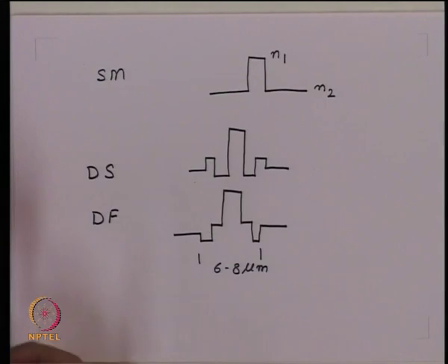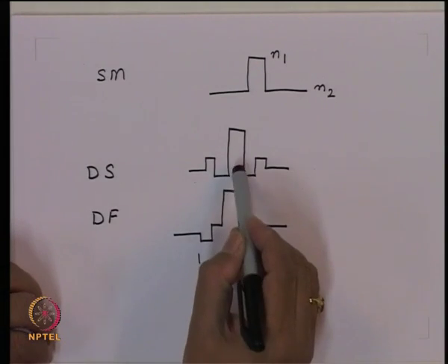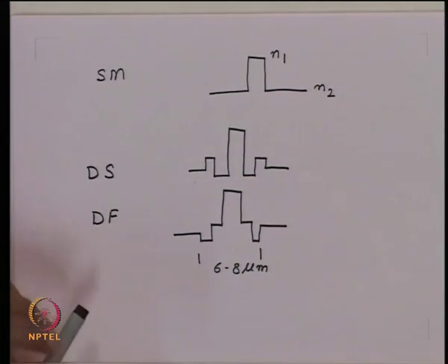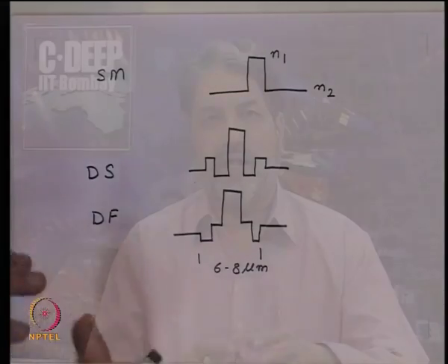So, obviously, the V number which you could define earlier cannot be defined for refractive index profiles like this. So, one has to find another means of characterizing the fiber. We know that the fiber is still a single mode optical fiber, and if you look at the field distribution of the single mode optical fiber, we know that the mode which is propagating is LP01. It has a maximum at the center and then the field dies down monotonically as we go away from the center of the fiber.